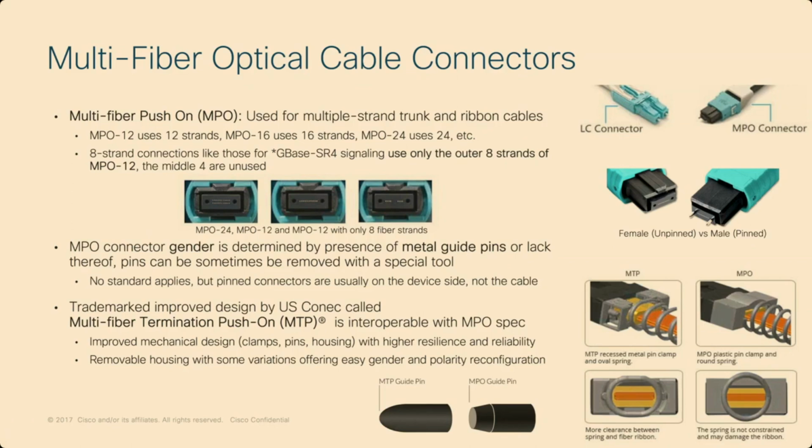It's also worth mentioning that the MPO standard is the standard, but then there's a trademarked version from US Conec called Multi-Fiber Termination Push-On, or MTP. MTP is completely interoperable with the MPO spec. So you can take an MTP cable and plug it into an MPO connector on a device, and it's no problem. They just made some mechanical improvements to the connection type.